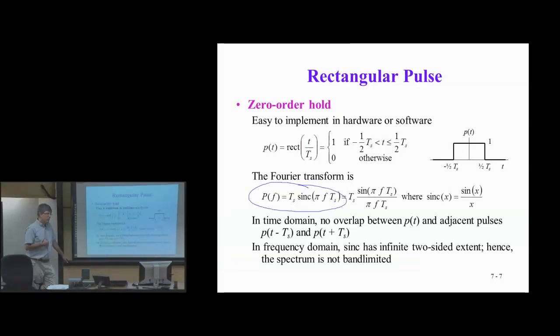I haven't derived that in a while. That's from memory. But every time you've plotted the magnitude response of the averaging filter, no matter what length it was, that stop band attenuation was always 13.5 dB. That's from previous lectures, and homework experience, and there's a midterm in there too. So here, 13.5 dB.